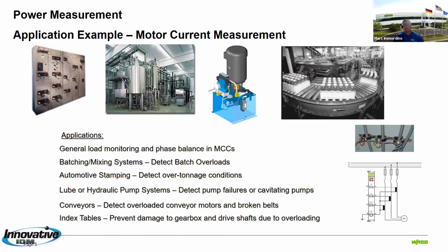So when we look at things like general load monitoring and phase balancing with MCCs, batch and mixing systems, so batch overloads, stamping. So like if you're stamping, obviously you get over tonnage conditions where something's not quite as binding potentially in there. Hydraulic pump systems, so detect pump failures or cavitating pumps. Indexing tables, preventing damage to gearboxes and drive shafts and so forth. So again, it's not industry specific, it's across many industries, across many applications.